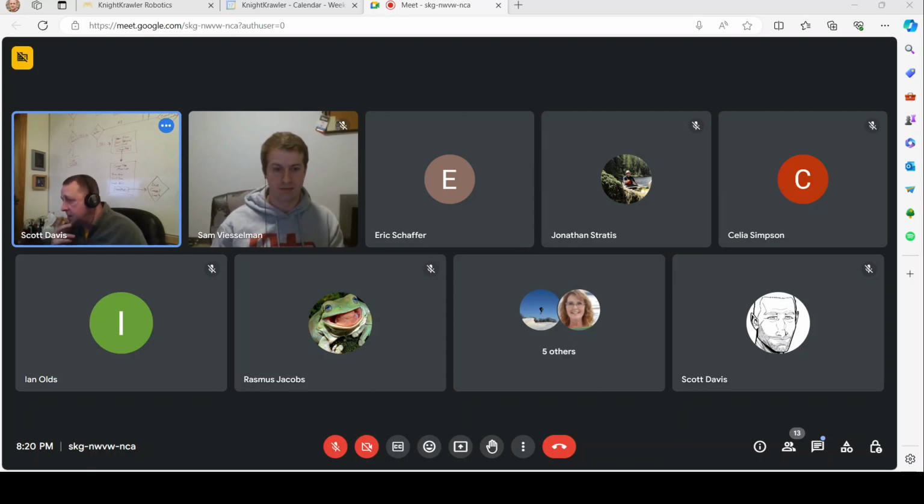Our plan is, step one, we're going to disable onboard position calculation with Photon Vision, instead just get out the raw April tag data. And then we are going to throw away any April tags that are not on the speaker, because we don't care about the other April tags for positioning. And then we're going to try to do some other filtering as well to discard. If we're too far away, we're not going to trust it. We're going to say we have to be within so many feet before we'll start trusting the April tags. I believe that's what Caleb, our programming captain, has as his current plan.